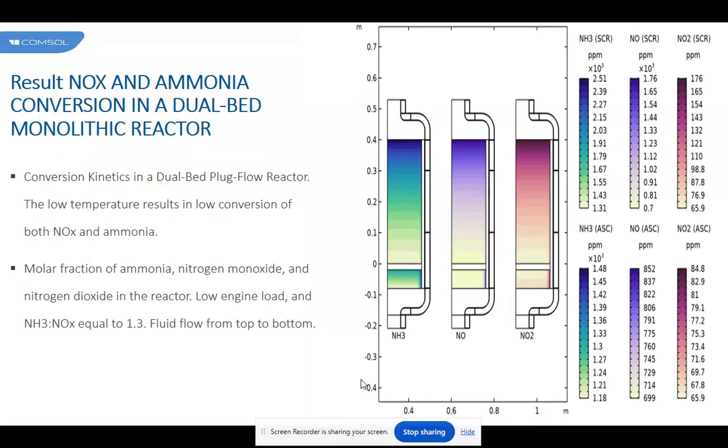As this increased temperature, the conversion increases in the reactor. Higher mass flow rate and higher heat source due to increased conversion gives a smaller radial temperature gradient. The radial temperature gradient has less influence at increased space velocities. For the highest load case, the radial concentration difference is thus lower due to the high temperature.